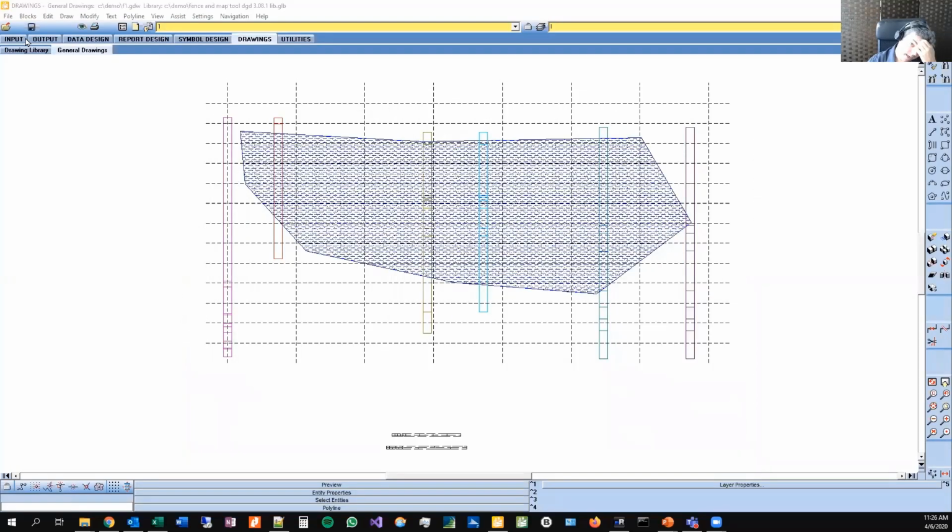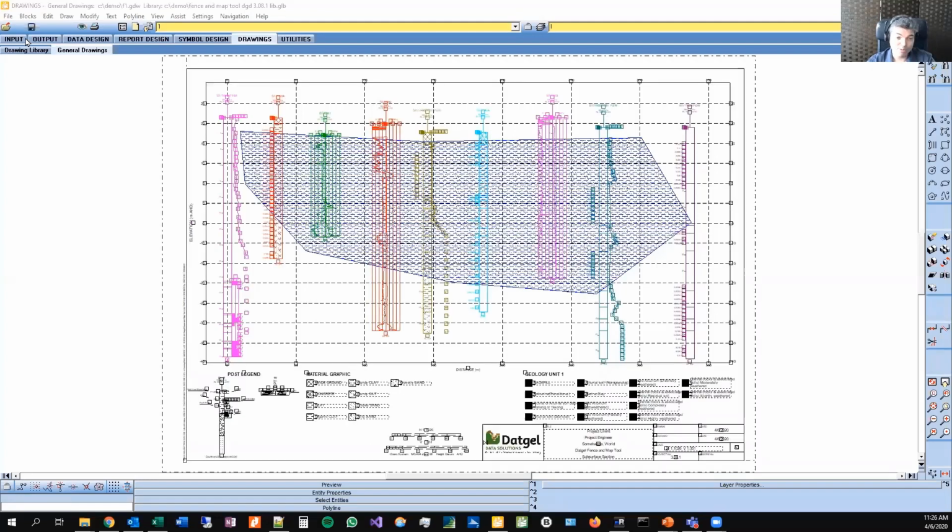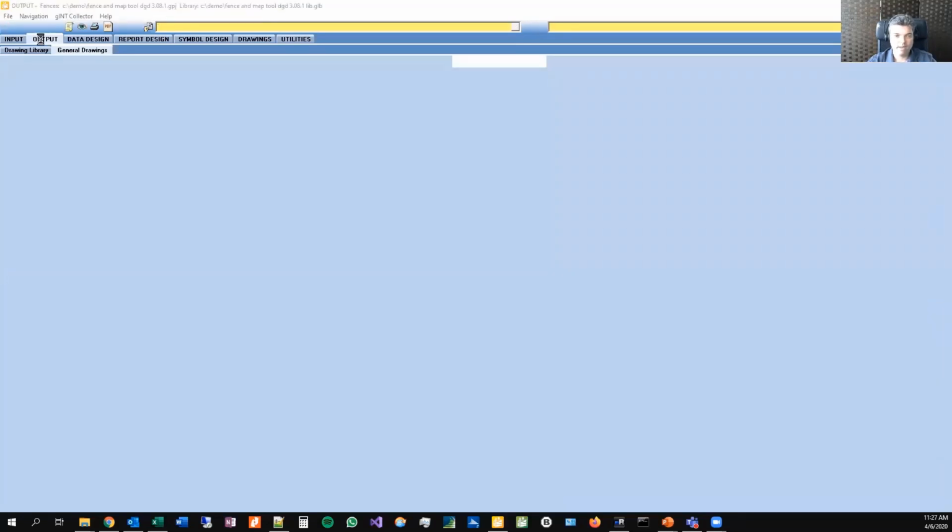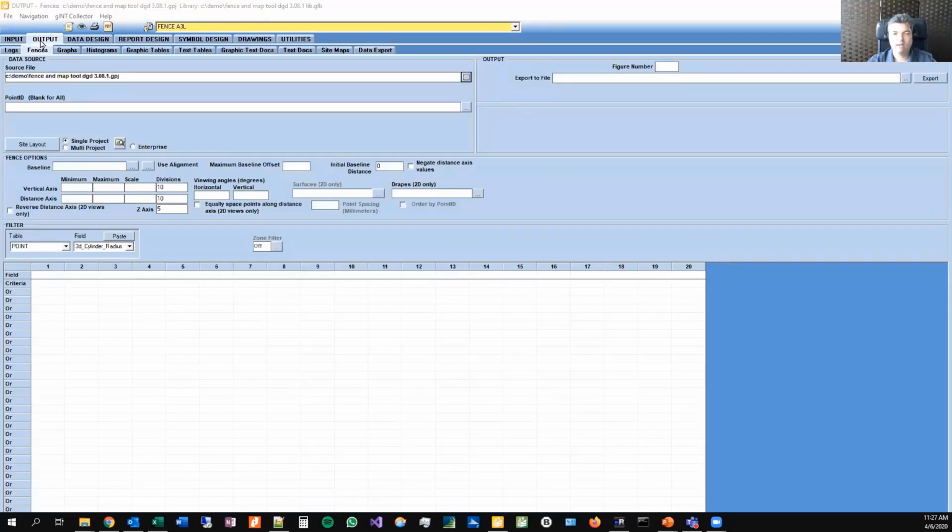All right, now other people will ask normally, and I'm sure that one of your questions in your mind is, okay, how can we automatically draw lines on the fence? Well, gINT has this surfaces functionality, which I'm not actually going to show you how to use today, but it can automatically define a 3D surface, and then you can display that on the fence behind your boreholes. Or you can do what I just did there. You can just annotate the fence. And actually the best place to create the 3D surfaces is in gINT Civil Tools, and then you can export them to LandXML and import them into gINT.